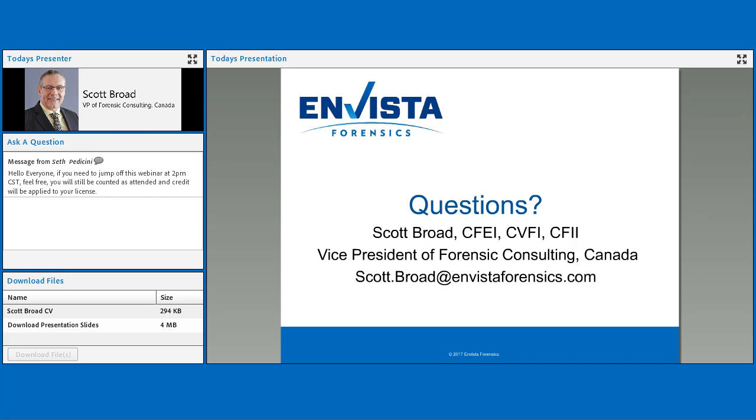So if a panel does last 20 years, and you put it on a roof that's only going to last 5 years, what's going to happen? This is an issue now, especially here in Ontario, with a lot of the big box stores where they slap these things on the roof, and now we're starting to see degradation of the rooftops. You've got to remember that these panels absorb heat. They're basically great big heat absorbers that transfer a lot of this radiant heat down to the rooftops themselves. And we are seeing some evidence to suggest that there is degradation of the rooftop. Now, that's a whole white paper unto itself, and it's something that's being looked into now.